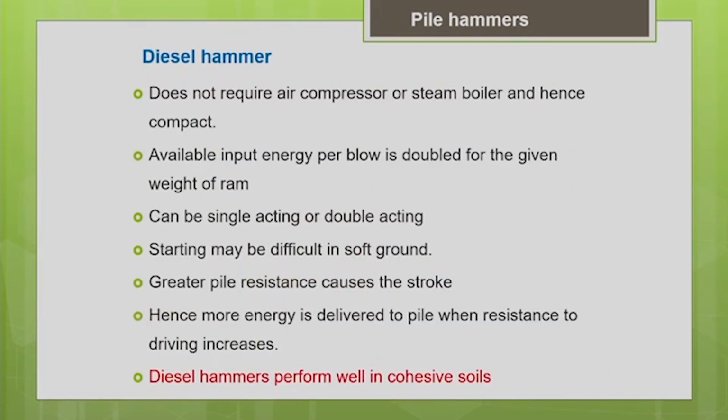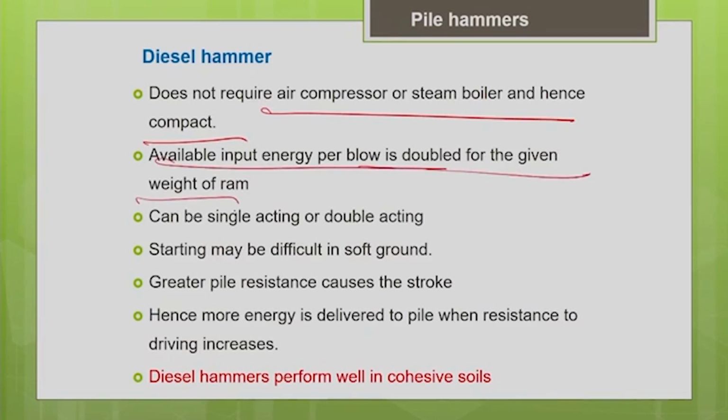The main advantage is it does not require a separate air compressor or steam boiler, and hence is very compact, as I told you, and the available input energy per blow is doubled for the given weight of ram. How is it doubled? Because of the explosive energy, we get additional energy for driving. It can also be either single acting or double acting.